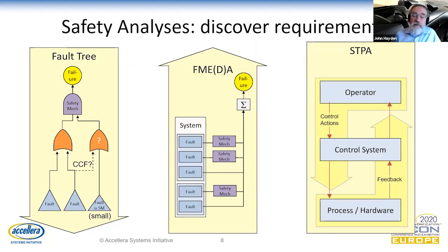And all of this has to be functioning in order for the system to be stable and maintain its intended state. So in STPA, what you do is systematically go through all of these messages looking for, say, incorrect feedback from a sensor or unsafe control actions with an unintended actuator message, and then evaluate all of them to see if it might lead to a loss.